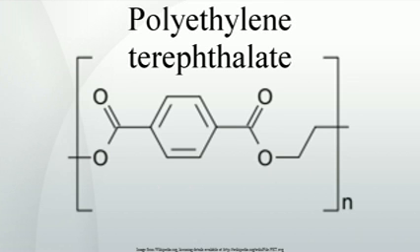Since this building block is much larger, 6 additional carbon atoms, than the ethylene glycol unit it replaces, it does not fit in with the neighboring chains the way an ethylene glycol unit would. This interferes with crystallization and lowers the polymer's melting temperature. In general, such PET is known as PETG, polyethylene terephthalate glycol-modified.